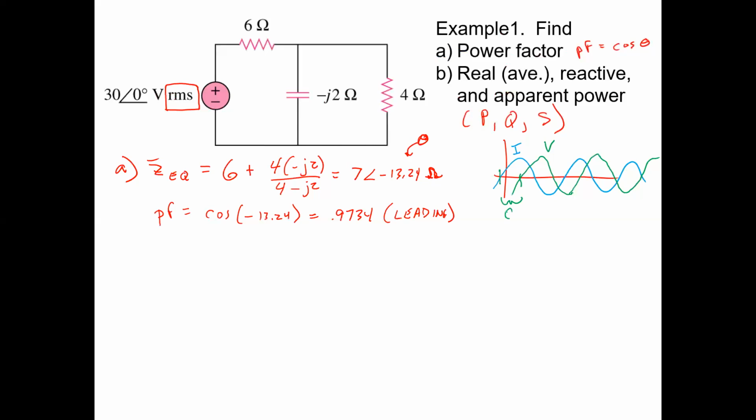You found that angle experimentally in degrees, and that was considered a positive angle. But it turned out when you did the impedance, because it's V over I, you got a negative impedance angle, right? And that's consistent for a capacitive load. And that's where the current leads.